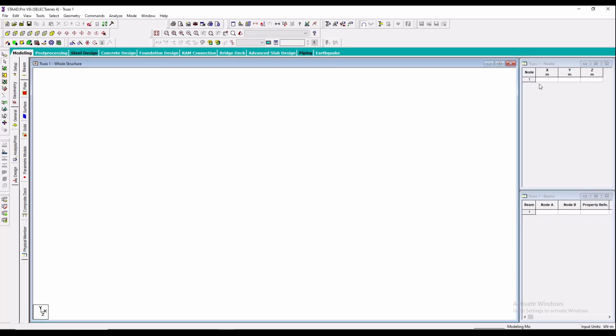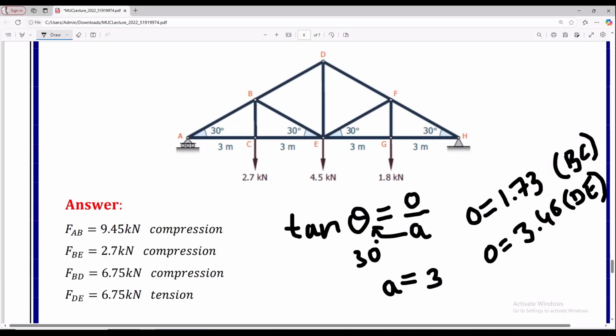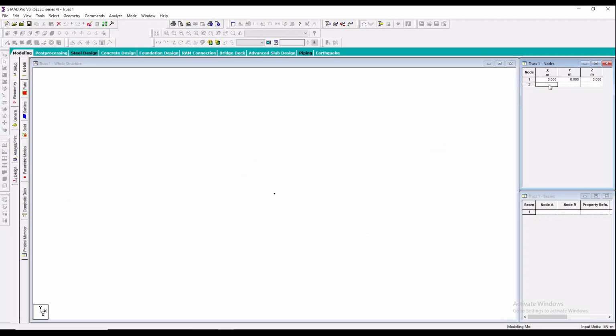So now I will close this default grid liner, and will create the model by referring to this coordinate system. First is 0, since from 0 I am going to start. If you refer to the picture, it is having a 3 meter span, 3 plus 3 is 6, plus 3 is 9, plus 3 is 12, right?